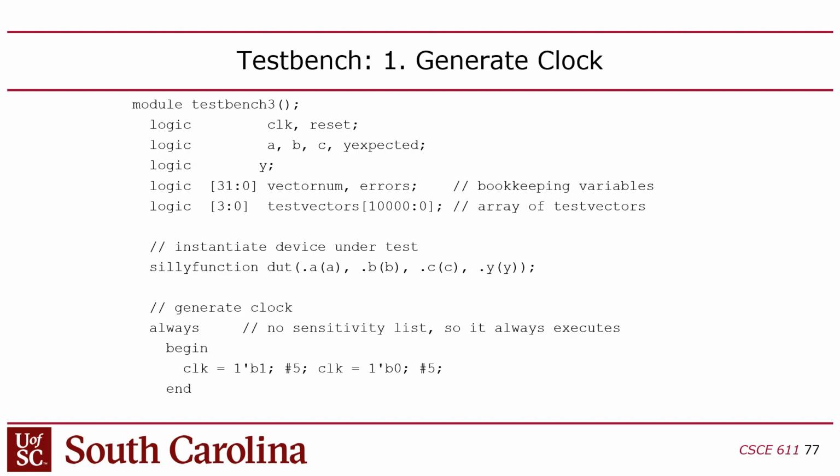Usually if you have an array like in C or Python or Java, you put the size of the array after the name of the array. Well, here you have to put it before. But this is where it even gets stranger. If you make a two-dimensional array in Verilog, then you put the other dimension after the name. This is also the syntax for declaring a RAM array.